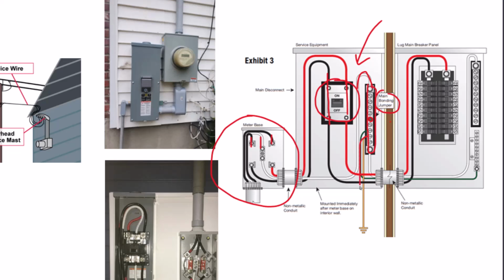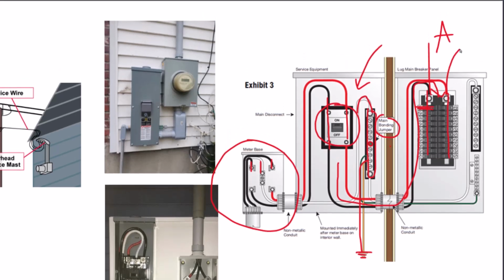And then you also have a grounding conductor here that typically goes into the ground, or it could go to a metal beam inside the building. Okay, and this basically grounds the whole system. And then all of this then goes into your panel board. Okay, and this is the hot leg that goes through, and the other hot leg that goes through. And each of these circuit breaker slots would then connect to the two phases in alternating sequence. So the first one, let's say this is phase A, this is phase B. The first one would go to A, second one will go to B, and then it would continue that alternation.